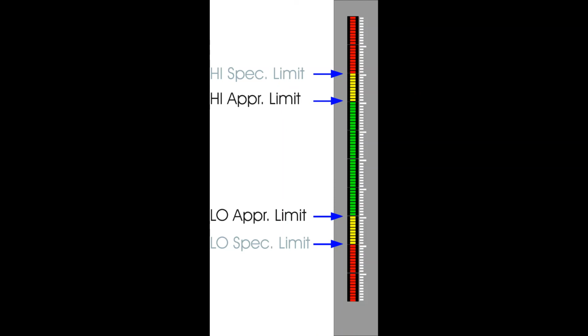The set points not only are identified by color changes on the bar display and the LCD display as the user sets this up, but also determine the status output conditions. Therefore, an output can be configured to cause a voltage change, which is the standard configuration for a bad part, or as an option, a relay contact can signal that the part is bad.